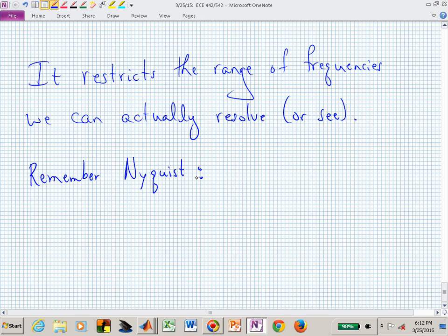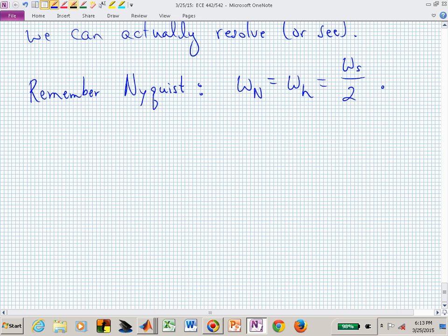And I'm going to ask you to remember Nyquist in terms of this relationship. Nyquist is maybe omega sub n, but I may refer to that as the highest frequency, omega sub h, that we can resolve, and that's actually just half of the sampled frequency. Have you had a course where you've talked about sampling?